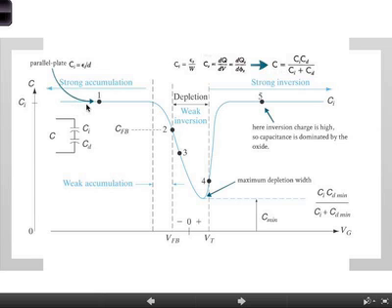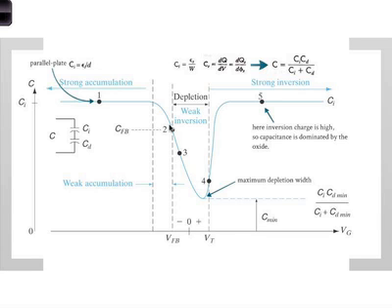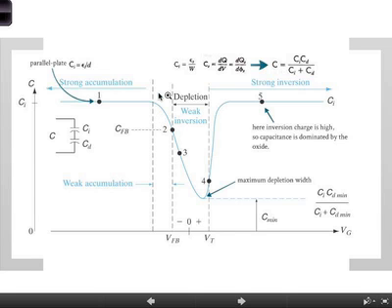Now, as you increase the voltage, of course, at some point you start going down. Why? Because now you're starting to induce depletion. As you apply a smaller and smaller negative voltage, or closer and closer to 0 volts, this starts pushing away the holes and starts attracting electrons. As you push away the holes, you're exposing the acceptor ions. So you get negative charges exposed, which are fixed. Now, of course, this number starts becoming smaller.